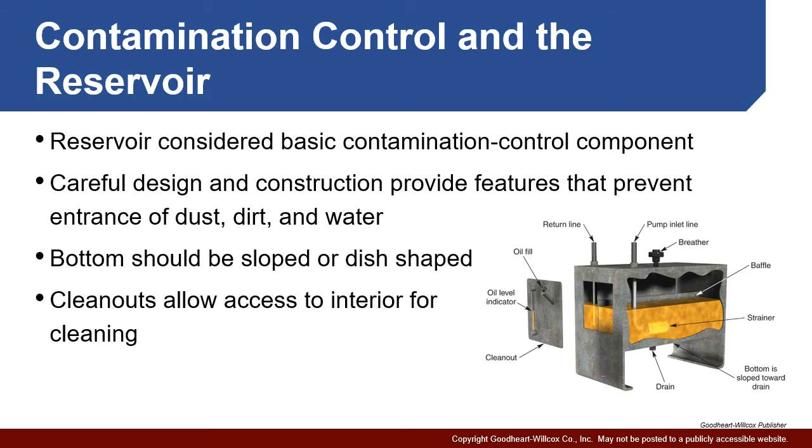Reservoirs are designed with a sloped or dish-shaped bottom with the idea of those solid contaminants going to one location, and then when you drain off the fluid, the contamination is relatively easy to be removed. If there's a major amount of contamination, however, just draining it out isn't necessarily going to be effective, and you'll see on nearly all reservoirs we have some sort of clean-out plate on the side, or perhaps the top is removable for you to actually go through and clean it out in a complete manner. That, of course, requires you to remove all the fluid, but in certain situations, if you have a lot of contamination, it's necessary.